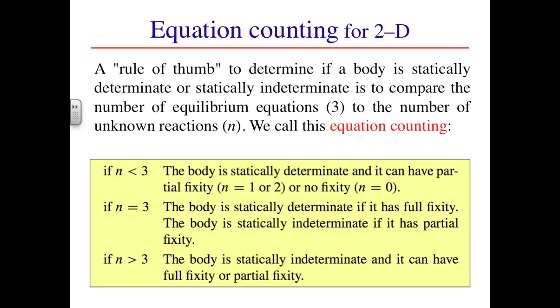If we are treating the same engine as a body, then there are three equilibrium equations, and n equals 1 is less than 3 indicates partial fixity with 3 minus 1 or 2 rigid body motions. As a body, the engine block is both capable of experiencing gentle rotations in the out-of-plane direction in addition to swinging back and forth in the horizontal direction.